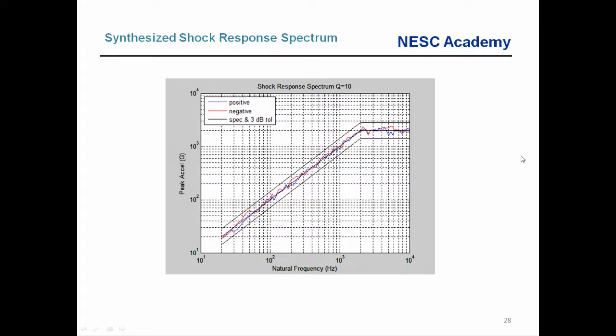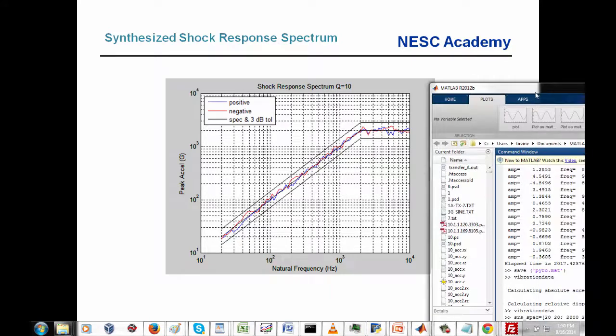So that's all looking good, and we're assuming here that the natural frequency of our structure is going to be 40 hertz or higher. Now, we could take the SRS of our signal and see what it is below 10 hertz, and we'd probably see that it starts to fall off with maybe about 12 dB per octave. So there is response energy below 20 hertz. But for 40 hertz or higher, we're good to go with this.